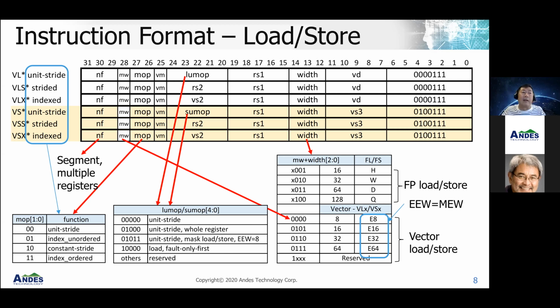So the data that you load can be in any order. It's the same for both the load and store instructions. And there are some special cases, where you can have a unit stride for the whole register, or different types of load store operation, including the load fault-only-first.